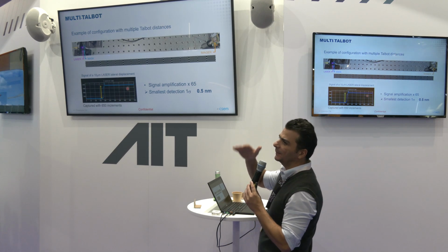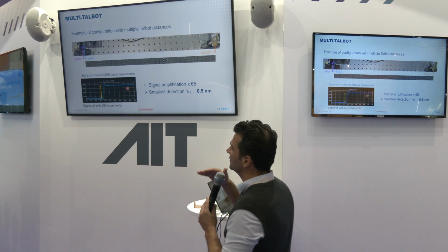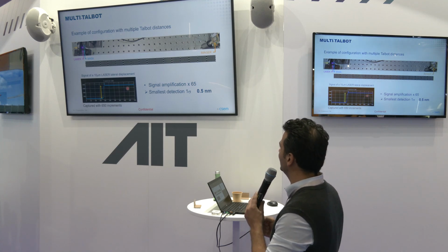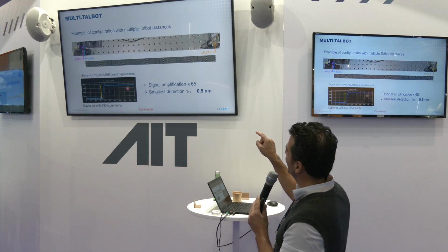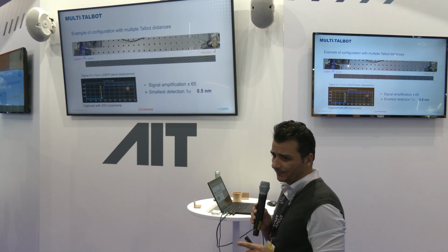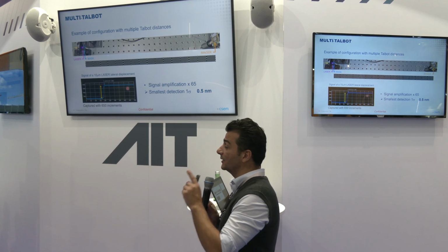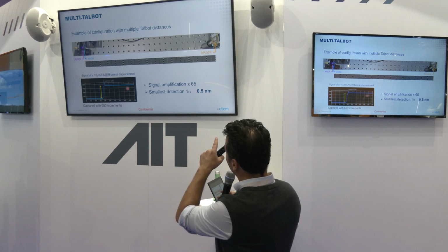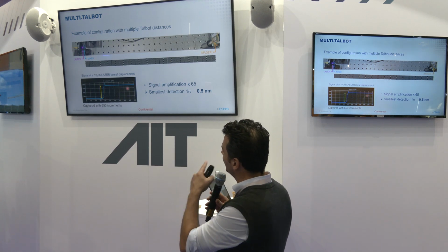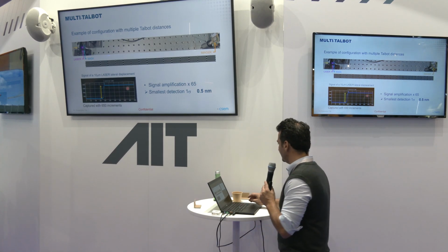We're doing a step for the imager of approximately 10 micron, and we are capturing this with 650 increments. So meaning phasing, we are getting 650 increments, and this leads us to a resolution of approximately 0.5 nanometer 1 sigma. Okay, and here we are measuring in 3 degrees of freedom. I'm measuring the XY plane, so everything which is perpendicular to the optical axis, and I'm also measuring the Z axis.